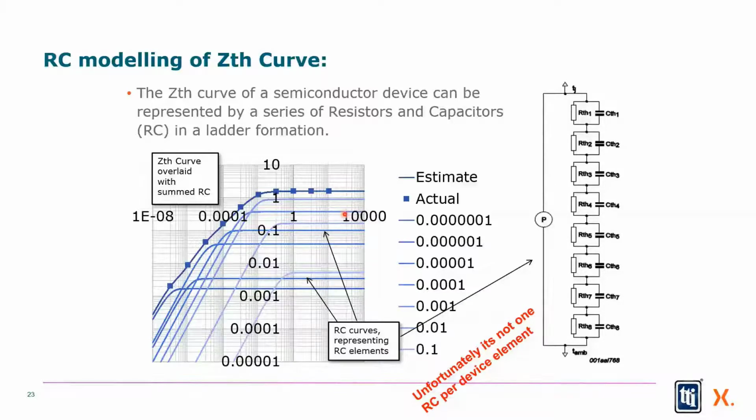small RC curves. If I then take these R and C curves, I can then create them in a model, and now I have a thermal equivalent of the actual measured curve of the device that I can now turn into volts and amps and plug into my simulation. So we do this part for you. This is all created. You just go and download RC values for these multiple pairs. Each of these pairs then goes together and creates the entire simulation model.